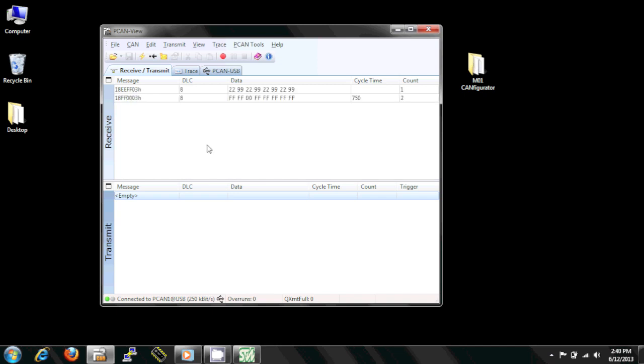And we see the first message, which is the address claiming message. And the second message now is the data. And we can see that this is indeed using the proprietary PGN FF00, which is hex for 65280. And the source address is 3. So it accepted our configuration and it moved the data into the third byte in the CAN message.